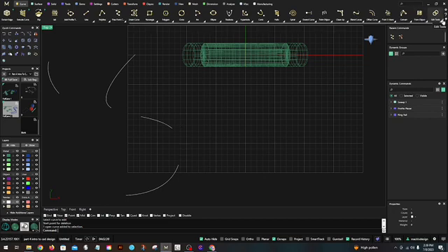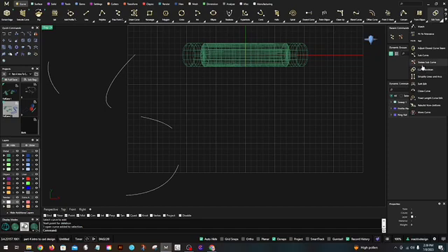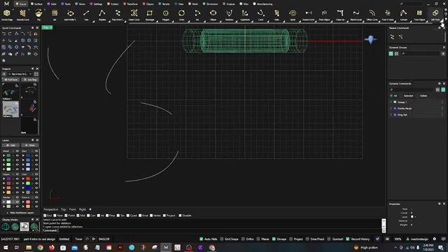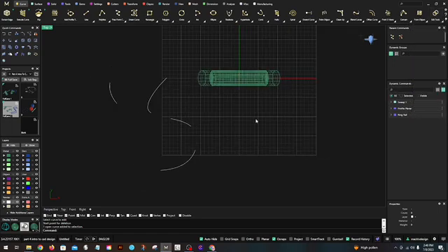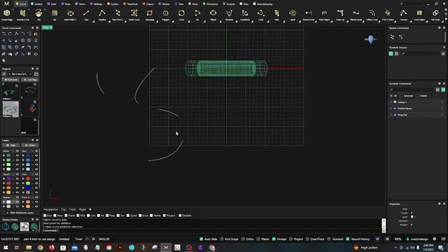Okay, what is next? Next is curve boolean, and I am going to come back to that because that one is somewhat extensive and I can't wait to show that to you. That's really useful, very, very handy. Okay, next I'm going to go to soft edit, simplify lines and arcs. I don't use that one. I would use rebuild.